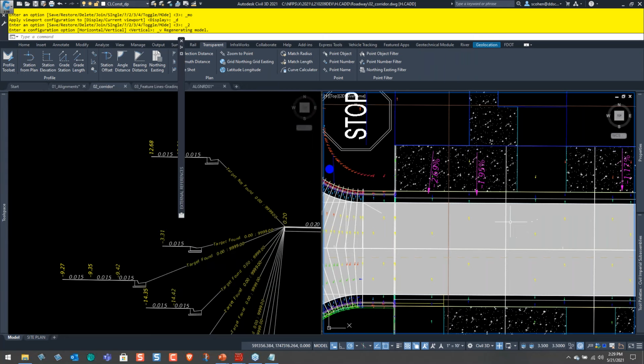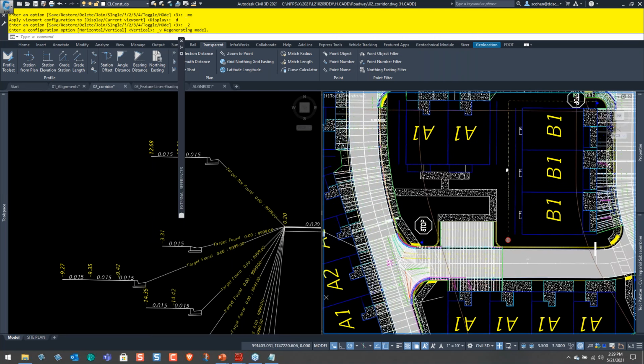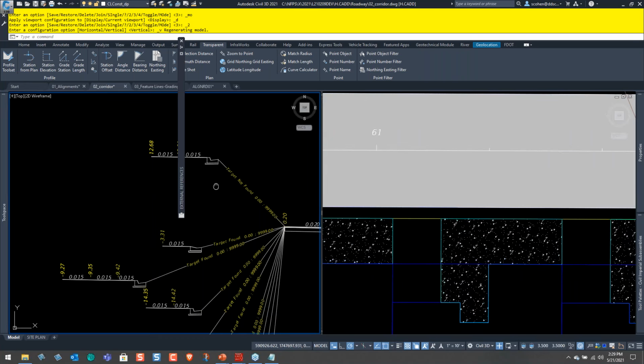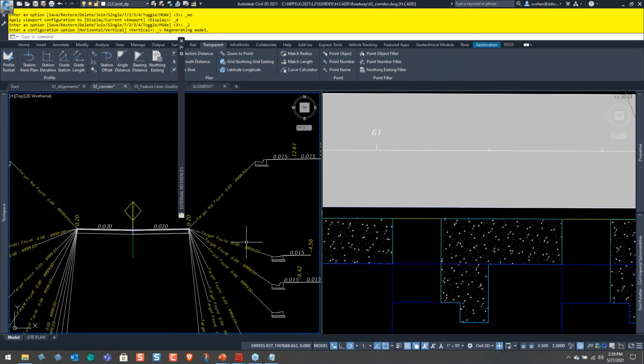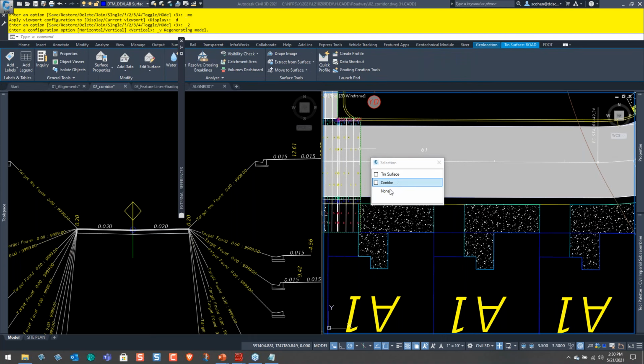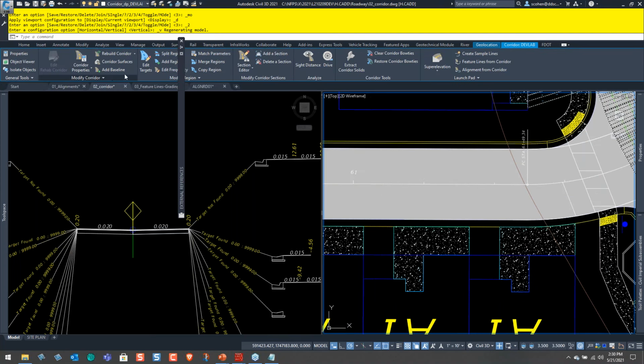When I'm in this scenario, and let's say I hadn't targeted this yet, okay? In fact, I think I have an area, yeah, right here. Let's say I want to target this right side. This is that Miami curb right side. It happens to be number 2, I believe, on this side as well. Yes, it is. So I'll go ahead and pick my corridor. All right, and then I will go ahead and add a region.